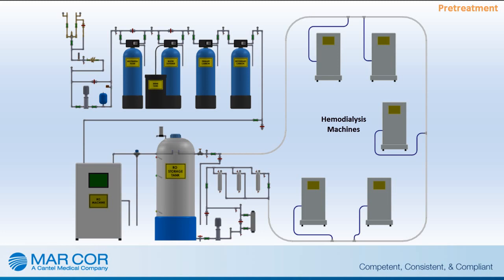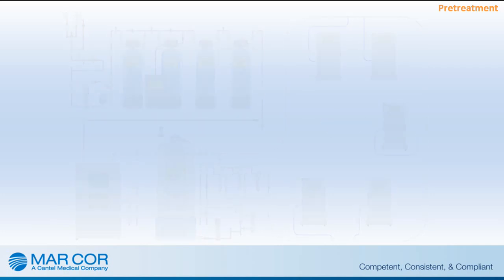In this video, we will cover the common pretreatment and post-treatment components typically associated with a reverse osmosis system used for the production of water for hemodialysis. We will discuss the reason that each component is part of a hemodialysis system and what daily checks, tests, and record keeping is associated with each component.